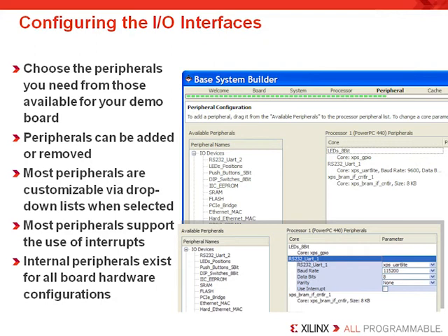To add a peripheral or external memory controller, simply drag it from the left-hand column to the right-hand column. To modify the core's parameters, you can simply double-click it after adding it to your system. Note that not all of the I/O interfaces are required for your use. Likewise, internal peripherals, that is, those peripherals that don't connect to I/O pins, can be added to any design on any demo board, of course as long as you have enough FPGA resources to add the component.